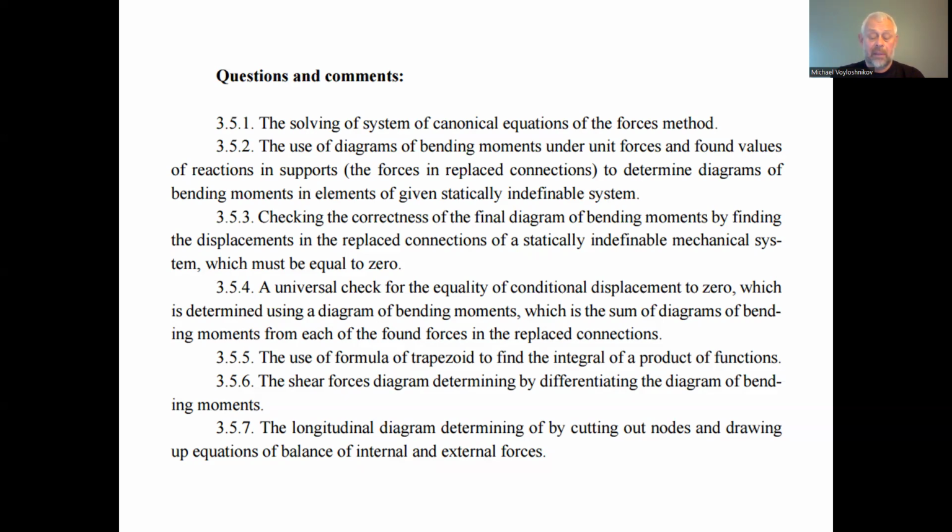To find these linear functions, we need only the magnitudes at the ends of each considered interval of the diagram of the longitudinal forces. And these ends we cut out as the nodes of the mechanical system and consider the balance equation for the nodes.